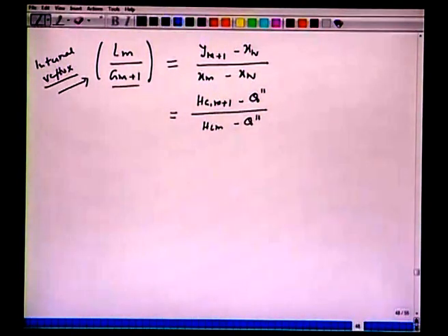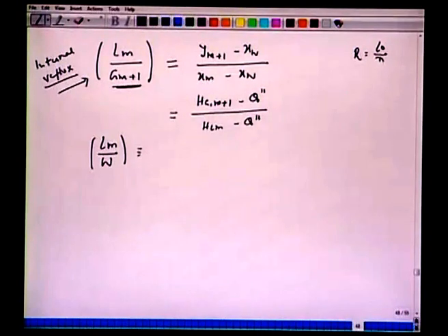We can also eliminate Gm plus 1 from the total molar flow rates to make it Lm over W. Okay. So this is equivalent to your R equal to L0 over D. We had the counting from the top, 1, 2, 3. So we had this L0, the external reflux, the liquid which goes inside the column relative to the product which we remove from the top.